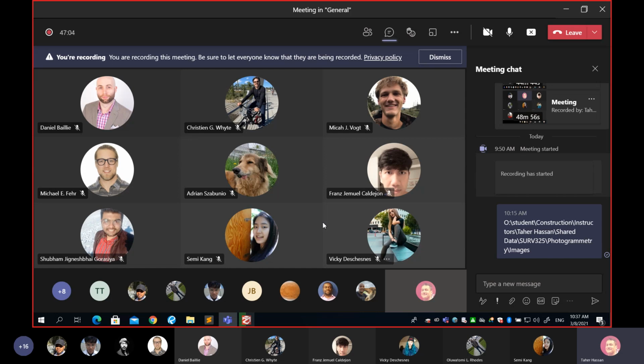When I hold my camera and take photos, should I take just one photo and then move very quickly very far, not covering the first area? Not really. You need to overlap your photos, and you are the one controlling the amount of overlap. If you're using a drone, that's a different business, and we may hit that point today.